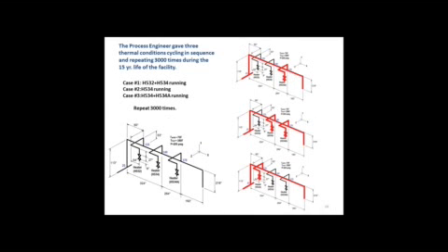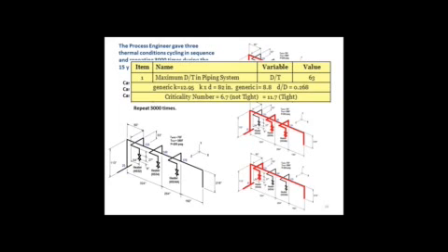Now let's go to a little bit more realistic condition, something that you generally would deal with. This might be your gorilla, especially if this was larger diameter pipe, because here you've got multiple operating conditions. So now you've got interaction between the different branches, and the branch flexibilities in a tight system will tell what stresses result when these systems interact.